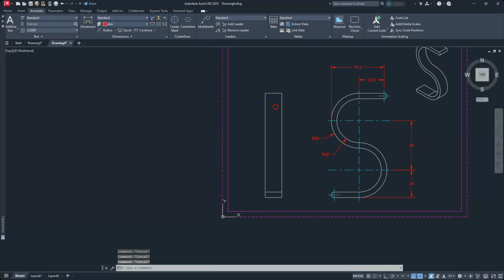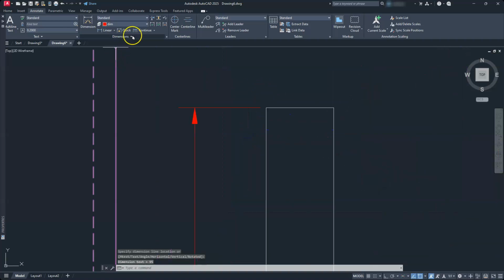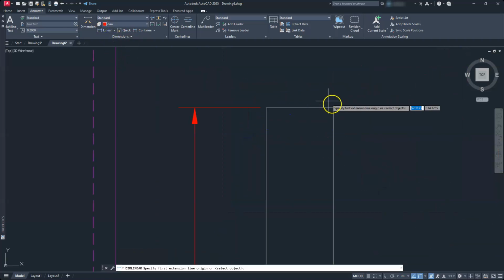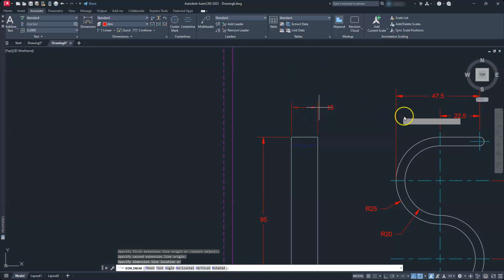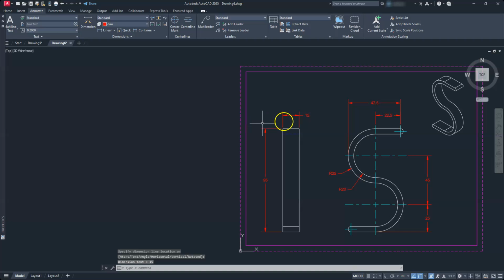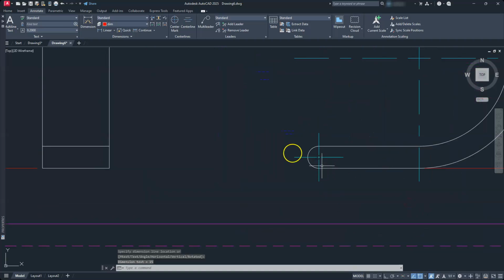Okay, let's go ahead and finish putting a couple of dimensions on here. So I'm just going to use a linear dimension. And then I'm going to give an overall dimension of this, right? So from that endpoint to this one. And then I'll select another linear dimension from this endpoint to this one. And that way I know it'll kick out to the right. Let me just make sure that it's in line. Okay. We need to put another radius dimension here on the bottom.